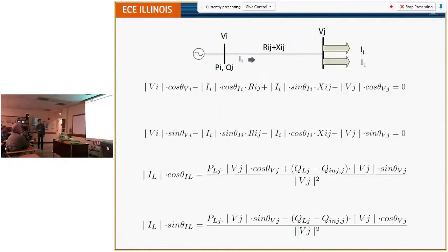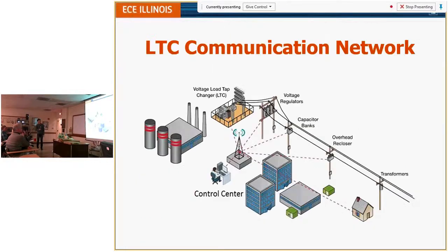This is a power flow equation here. It might not look familiar to you because this is in distribution. Because in distribution, usually it is a radial network. You don't use Newton-Raphson because it might yield an ill-conditioned matrix in that case. Okay, so sorry, 1 second.